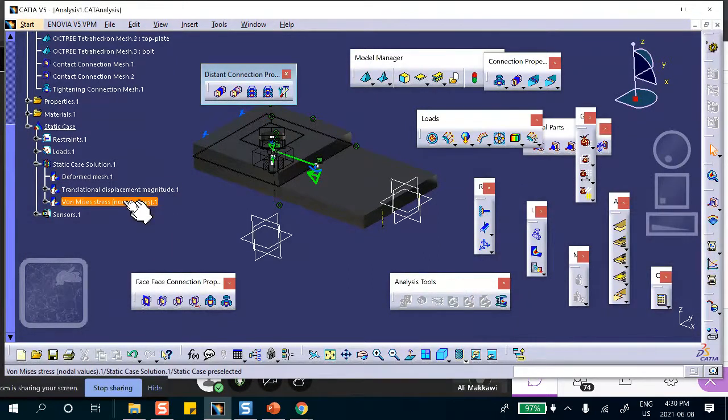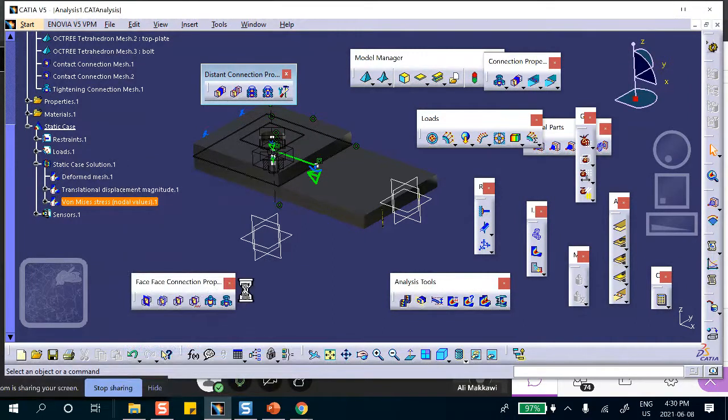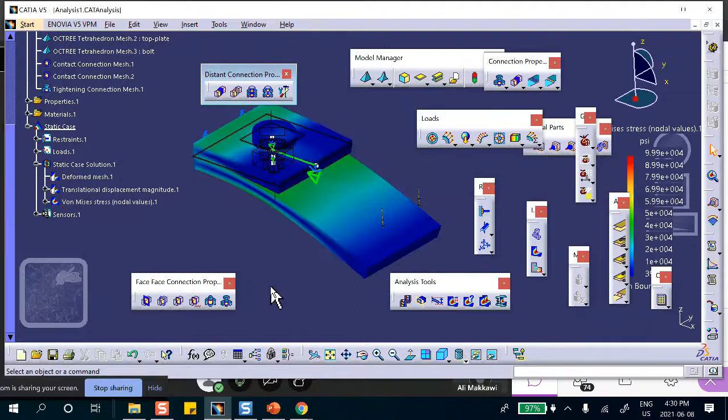There we are. Let's look at the stress pattern, which was checkerboard before. Yeah, that's better. Definitely that's better. The first one is total junk. This one, I have no idea, because I have to do a mesh convergence study.